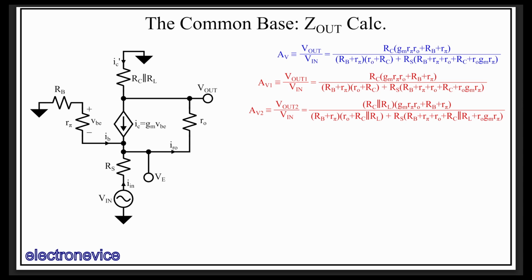First, we note that this circuit can be modeled as a perfect amplifier with Vin on the input and gain of AV1. This perfect amplifier, represented by the triangle, also has 0 output impedance. We then add a series impedance placed after the output of this perfect amplifier labeled Zout to model the currently unknown output impedance we're trying to derive. Note that Rs does not appear in this diagram. That is because the effect of Rs on gain from the Vin perspective is folded into the gain of the perfect amplifier. This is valid because our circuit assumes a Vin perfect voltage source going into Rs.